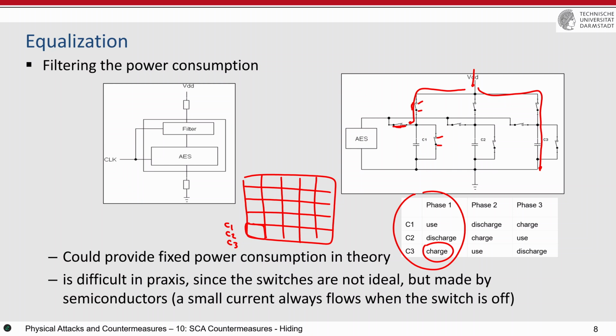We said all of this, again, if you put the EM probe at the top of the chip, then it will be also easier to perform the attack. But if you have the capacitors like this, smaller tiles, then if you put the EM probe at a smaller tile, then again, the attacks might be easier to perform compared to power consumption. But because again, everything is local, then you see all the emissions of charging and discharging these small capacitors. Then you will have also noise into your measurements.